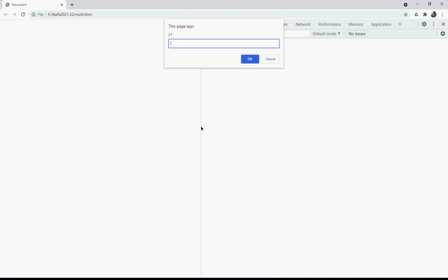I require x1 0. I require y1, that is also 0. x2 1000. y2 0. Okay. So it is asking now second element. So area is 100. Modulus of 2e5.